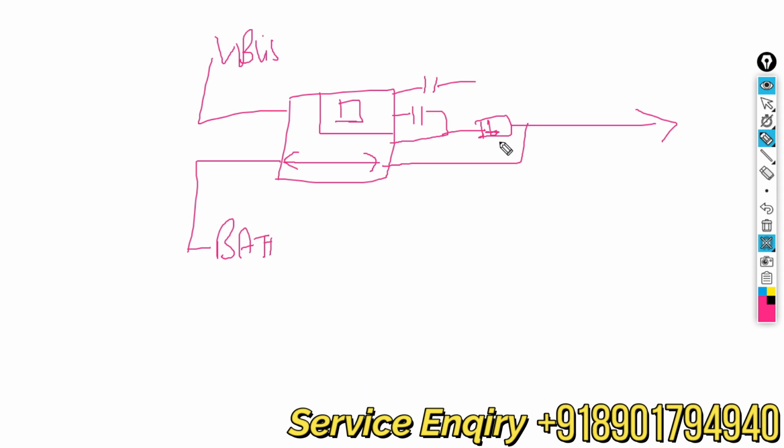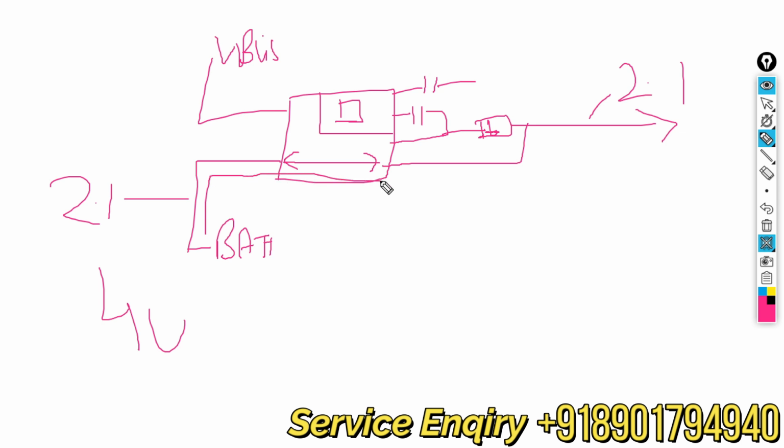That's why when you measure the VBAT voltage, it's 2.1, a similar voltage, you will get 2.1 because this line has come out. But when we inject the DC power supply with 4 volt, the 4 volt goes to this line, and through this line it directly bypasses this and goes to the VPH.